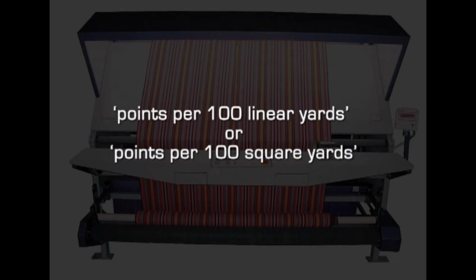In general, the acceptable level of points per 100 linear yards or points per 100 square yards is different for different fabric types. For example, for cotton twill or denim, it is 28 points per 100 square yards for an individual fabric roll, and for all synthetic fabrics it is going to be 20 points per 100 square yards for an individual fabric roll.